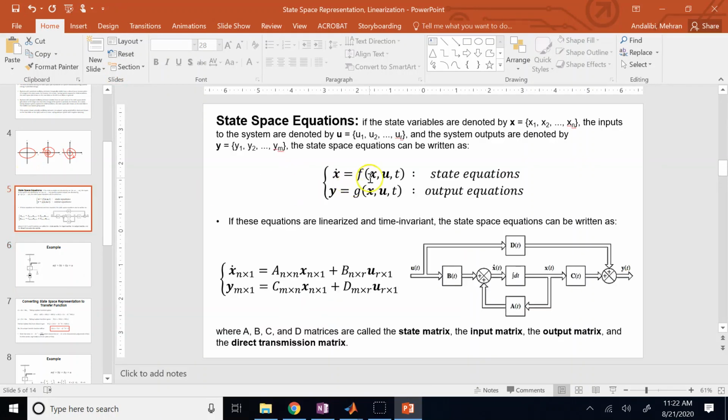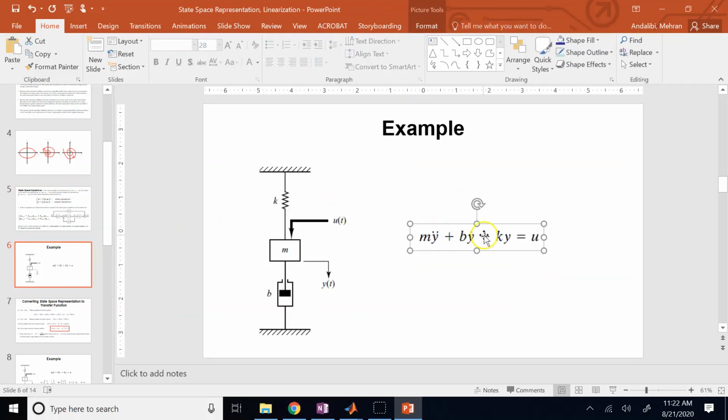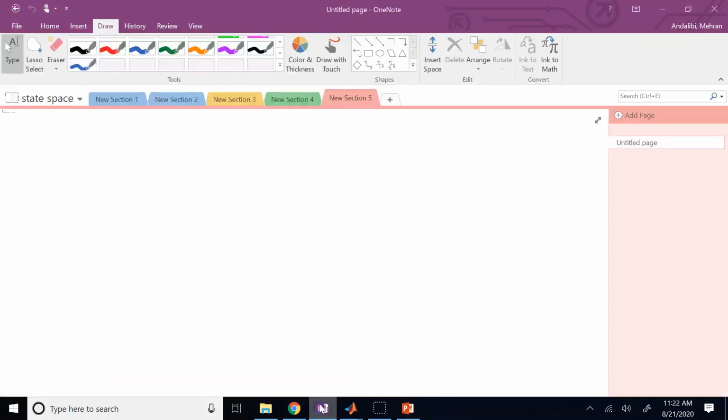But now, just to mention that this method works for nonlinear systems, I want to show you what happens if one or several of these terms are nonlinear. So I use a nonlinear mass spring damper system: m y double dot plus b y dot squared plus k1 y plus k2 y cubed is equal to 0.